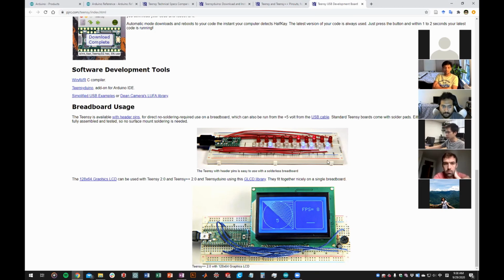We just have a breadboard here. Maybe the bottom picture on the right side is clearer. A breadboard is connected only in its own side, right? It's divided in the middle. So you solder a row of male pins to each side of the Teensy, and you just plug it in at the middle. Then you can connect from the side to access those pins.